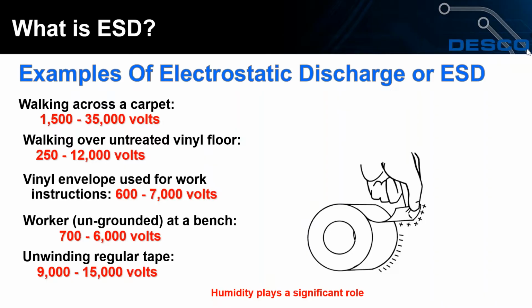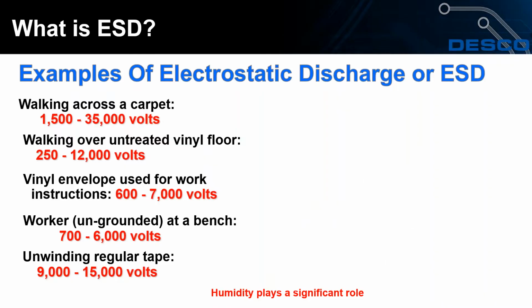Another thing that contributes to charge generation, or keeps it lower, is the relative humidity in the environment. The higher the humidity, the lower the charge will be. Consequently, the lower the humidity, the bigger the charge will be. So keep in mind that depending upon where you live and the time of year, you could have low humidity days where you're generating a lot of static and getting shocked a lot. Or if it's really humid, you're not going to feel as much charge, or things aren't going to get charged up as high.